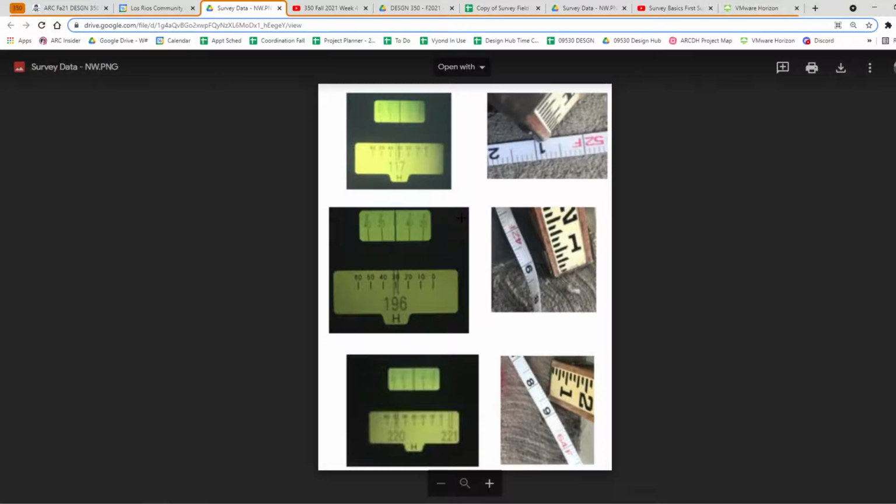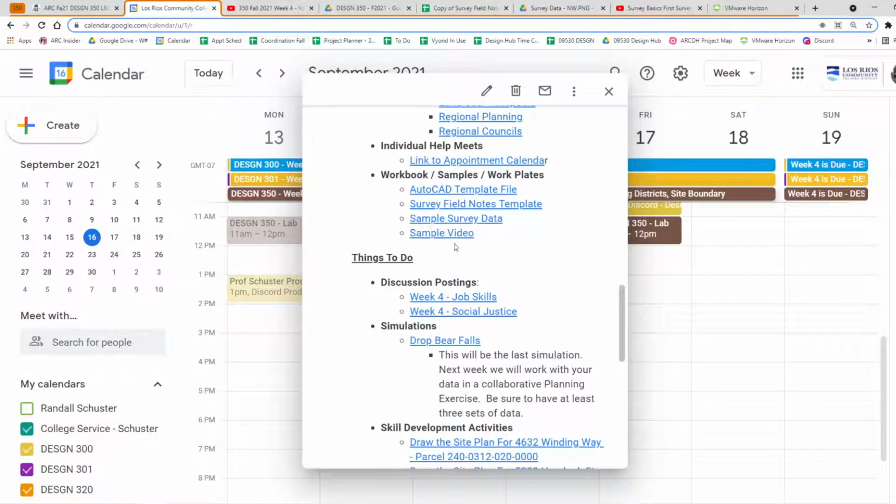And so, here's the azimuth readings, and you should know how to read those by now. And here is the distance reading. So it's the tape measure from the theodolite to the rod. And some of them aren't super easy to get, but you can kind of estimate and get kind of close with it. Okay, so you've got at least these,